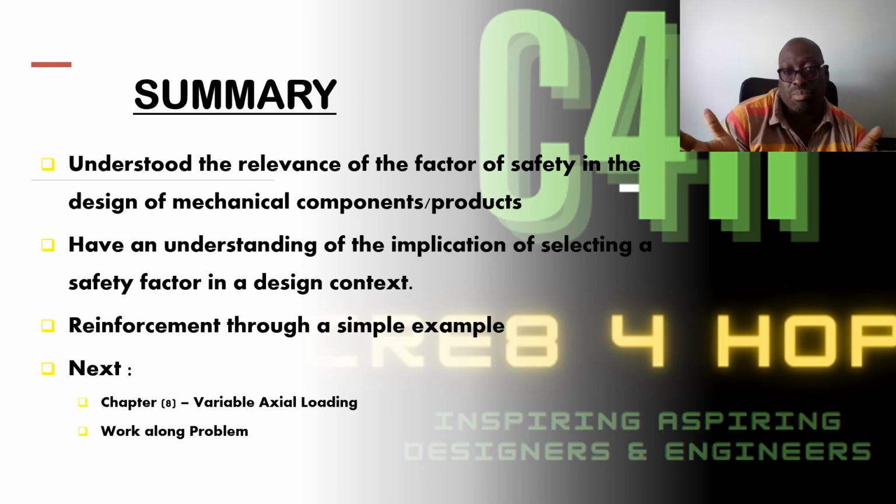We've also had a look at the indications of selecting the safety factor. Again, the larger the safety factor, the greater the certainty of its operability or its deformation within the elastic region of the material. But there's also an issue in terms of over-engineering the component, thus increasing the material allowance to a state that the component becomes very, very heavy and not ideal for the product.